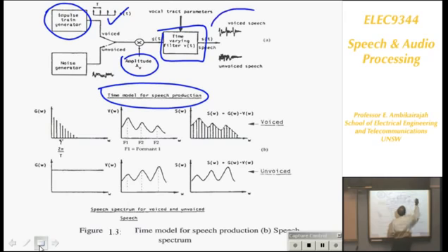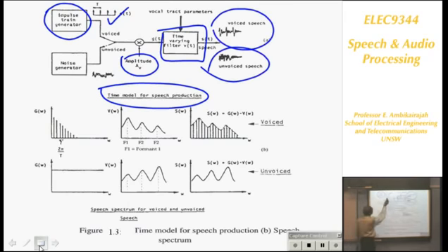If you look at voiced speech, it looks like this, and unvoiced looks like this, for example. And we look further. Let me look at that point: what is the spectrum at that point? If I get equal pulses separated at equal distance, the spectrum will be decaying like that, at 2 pi over T. So it has a fundamental harmonic, second harmonic, third harmonic, and so on.